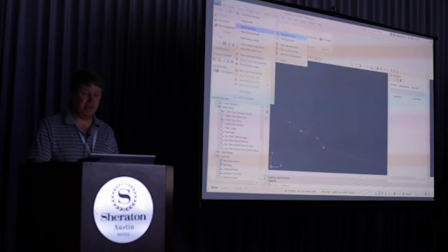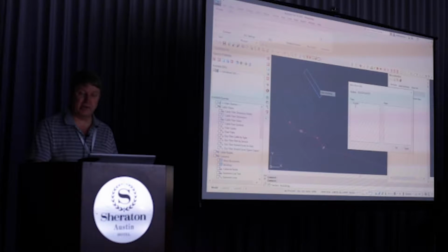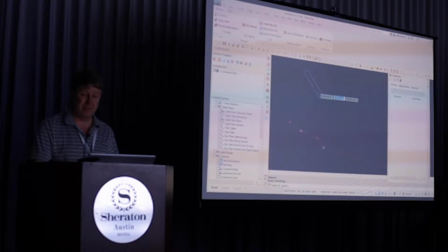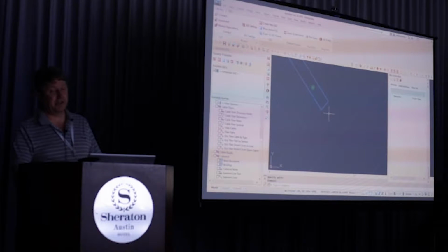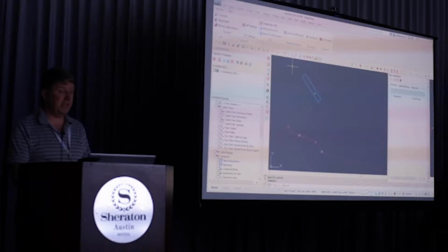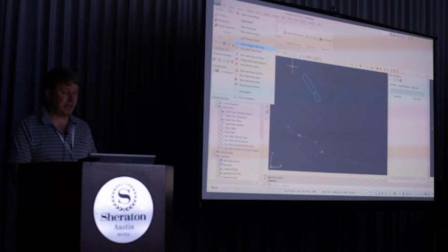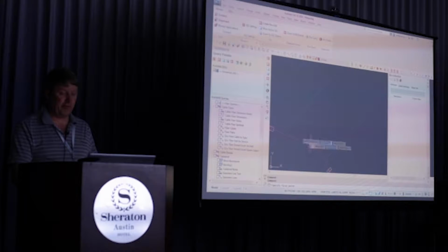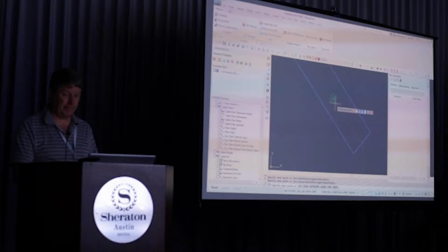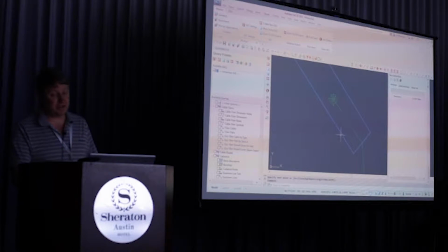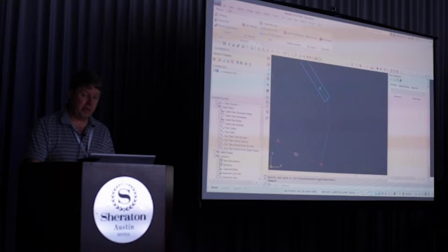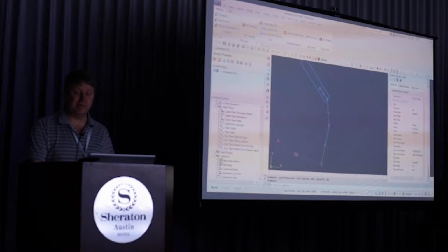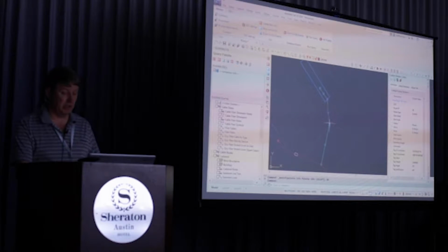So what I'll do is add a new fiber room, and it's in a building, and it's in a particular room. So I'll add it into that particular building. And we're now going to place, I'm going to do a freehand cable route in this case. Just to make it fairly easy, it will do the automated snapping for you. Now if I look at the information, it has already started to capture some information, but the connectivity is not built yet.